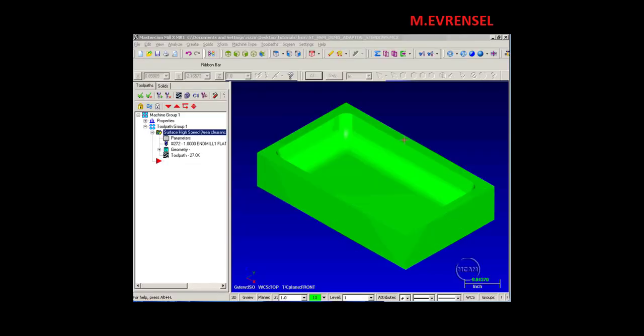For the toolpaths that use constant Z-cutting, those are core roughing, area clearance, and waterline finish. We have the ability now with surface high-speed machining to use adaptive step-down. Those constant Z-cutting toolpaths tend to work very well in steeper portions of your part, such as 30 to 90 degree walls. However, when you get into more shallow areas, they tend to leave very large stair steps.